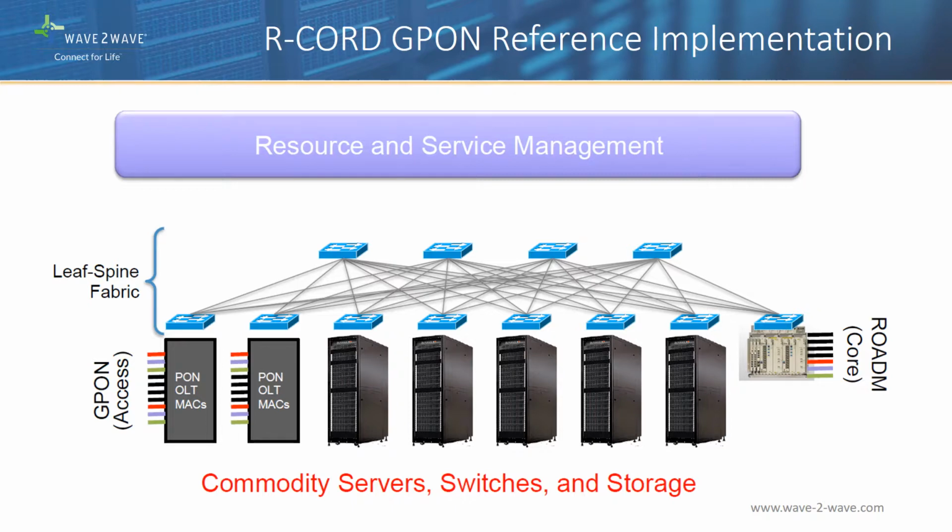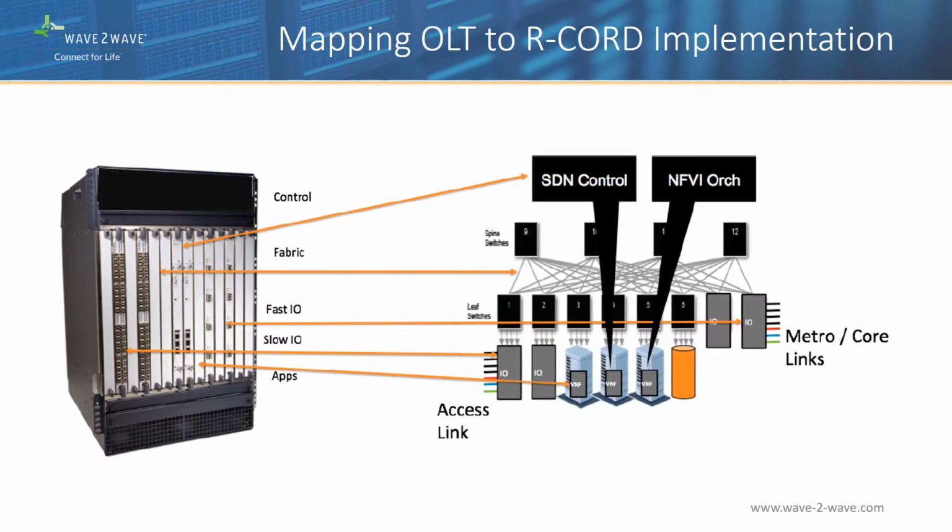Next slide, please. A legacy OLT-NE is a chassis that has power supplies, fans, and a backplane. The backplane is the interconnect technology to send bits from one card or blade to another. The legacy OLT typically includes two management blades for 1+1 redundancy, two or more uplink blades or the Metro I/O interfaces, and the rest of the slots filled up with line cards or the PON access I/O interfaces. In GPONs, the line cards have multiple GPON access ports.